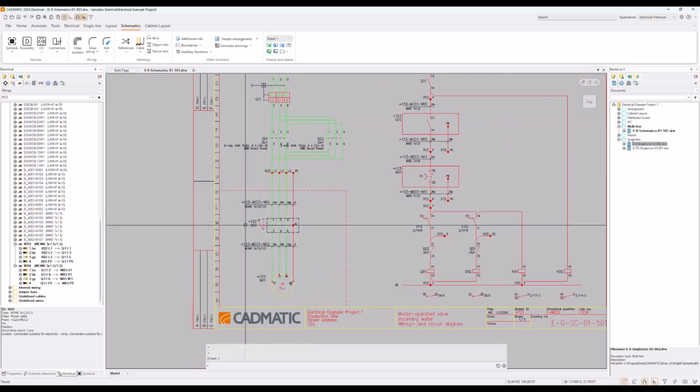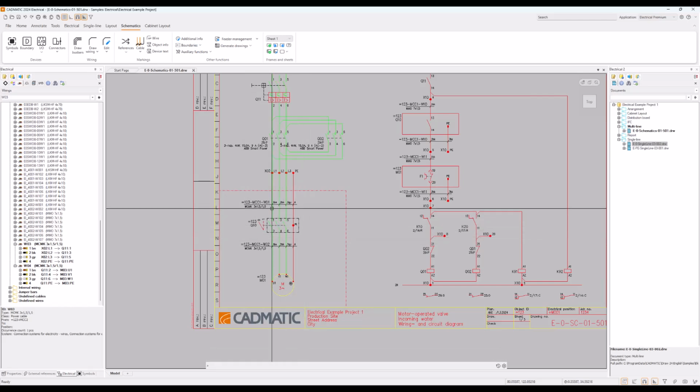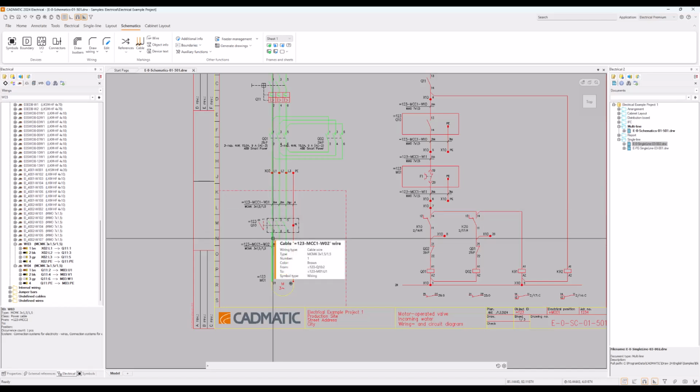There is the 123 Q10 for the safety switch, and it should be the same way for our new safety switch, and you can check even these from and to. So you can see that to information is 123 Q10 and pin number 1, and when the next cable wire is going from, it's 123 Q10 pin number 2.